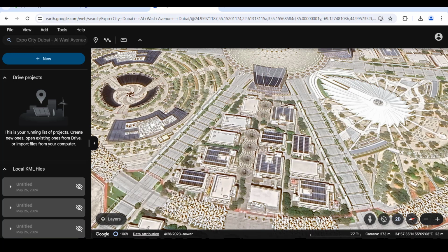If I link this file in this file, I will get the correct location in this file also. In this file I'm working and linking this building, and it will come at the exact direction and exact location if the coordinates are shared from one main federated model.